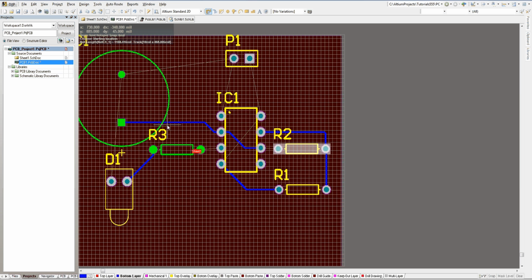Okay, and as you can see, Altium Designer makes it really easy for you to make all your connections. I mean, most PCB softwares do, so I don't think it's anything new. There you go, that's the capacitor connection. We're gonna go around, and one thing you can notice is the clearances are always respected, and these are set in the settings as I showed you. So there you go. I forgot to double click right there, and there you go, that's your connection.